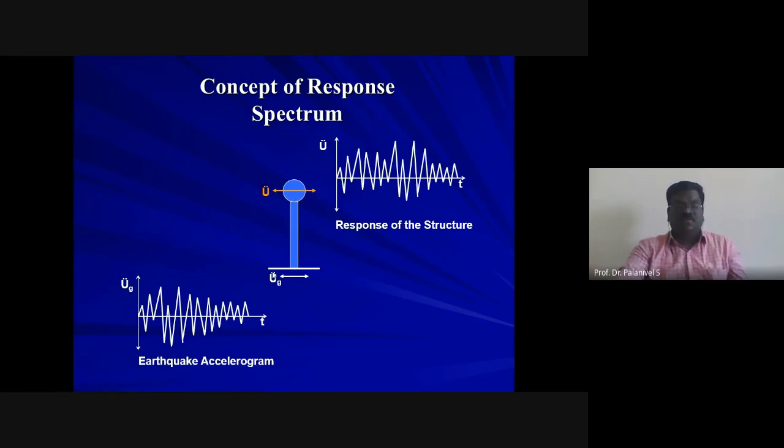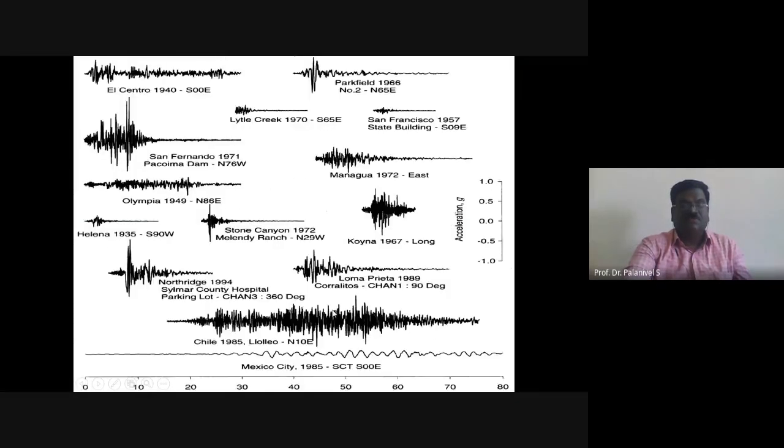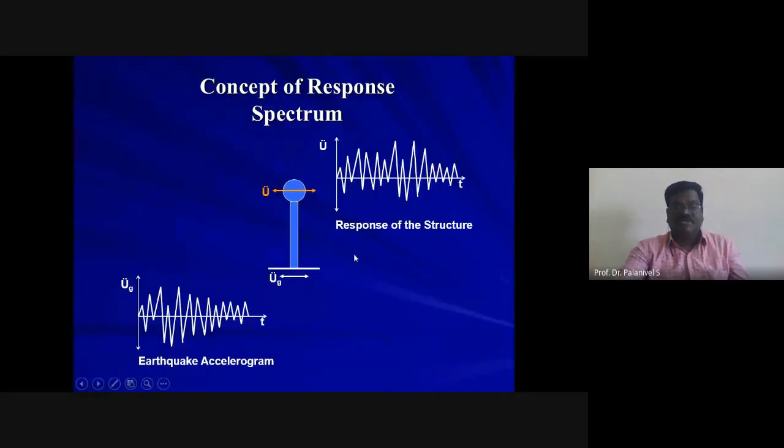Damping. What I am doing is giving a time history at the base of the single degree oscillator, with a particular stiffness, mass and a particular damping. I am giving say 5% damping. I am giving a time history, like the several time histories I just showed you, which all over the world are used as the earthquake accelerogram. It is a time versus acceleration plot. So the time history I am giving here at the base.